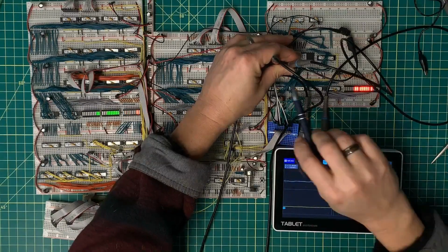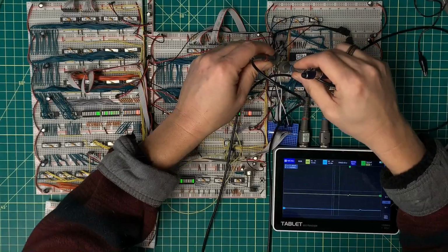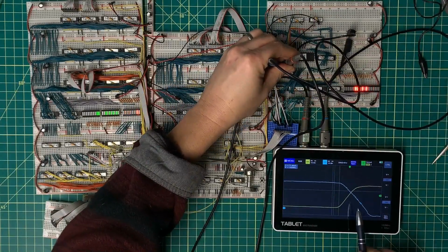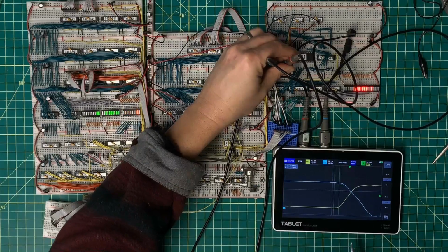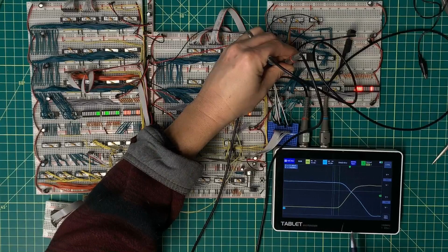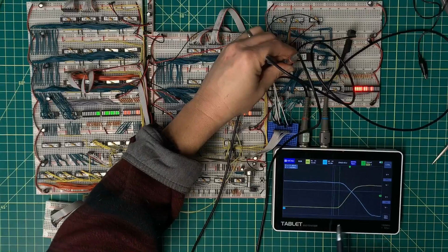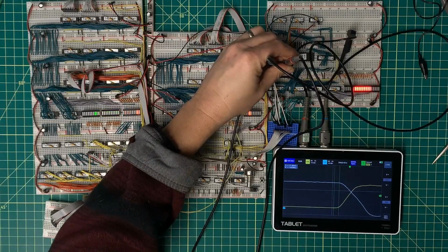The other thing I tried to do is swap the probes, meaning that I went from one measuring point to the other in an effort to see if the problem followed the probe or if it remained with the pin configuration that I was plugging into. It remained with the pin configuration I was plugging into, so the settings of the actual probes really have nothing to do with it. This is really more of a measurement of what's going on the breadboard.